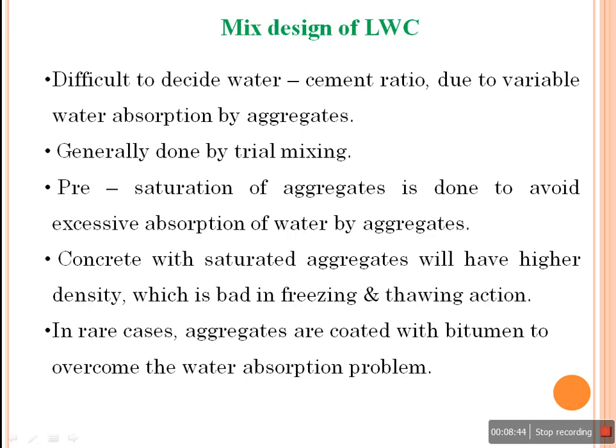Let us see the mix design of lightweight concrete. It is difficult to decide the water cement ratio. Generally, with experience, you will have a very good idea of what water cement ratio has to be chosen because of the variable water absorption capacities of the aggregates that are available. Generally, it is done by trial mixing.